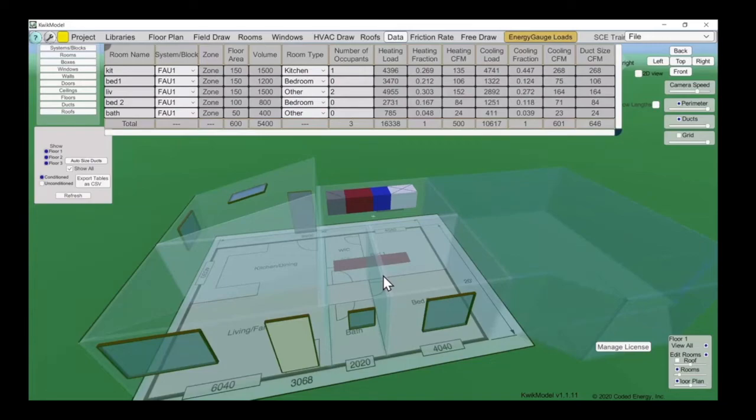What air is going past the thermostat? Okay, we'll talk about that in a little bit. But, all right, so we want to ensure the 601. In order to ensure the 601, we have to make sure that the resistance of the duct system is not more than ½ inch static pressure, okay? So now we're getting into manual D duct sizing.